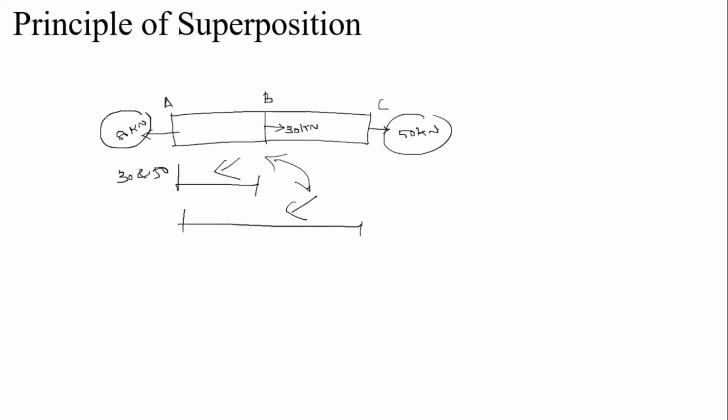So, now we are going to discuss the deflection del L. Already we discussed in our previous video, del L is equal to PL by AE, right. P is the load acting on the section, L is the length of the section, A is the cross sectional area of the shaft, and E is Young's modulus. The area of the cross section of the bar and Young's modulus both are constant, so take out 1 by AE, right. Here the load and length change according to the sections, right.